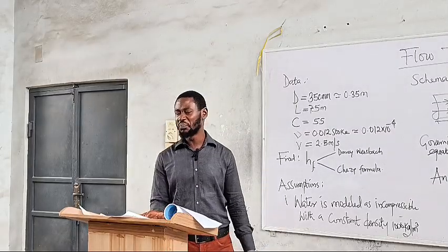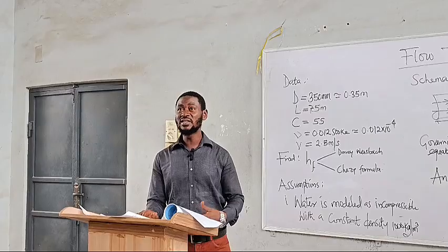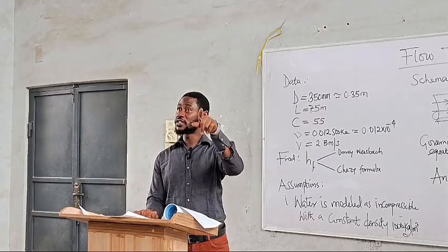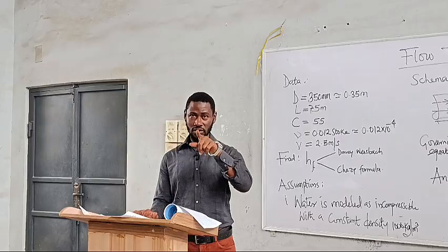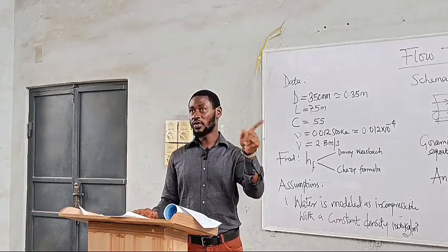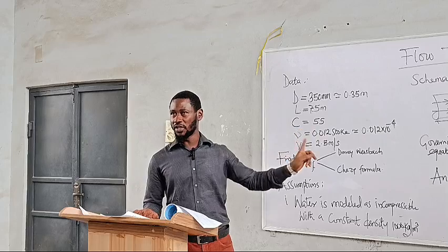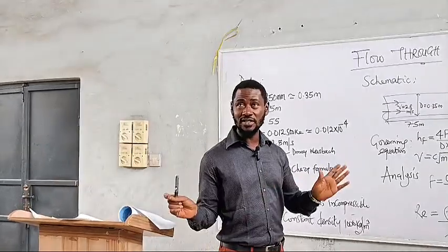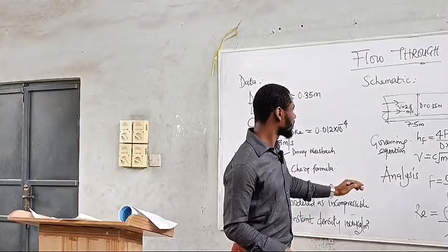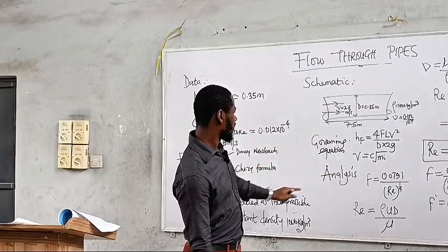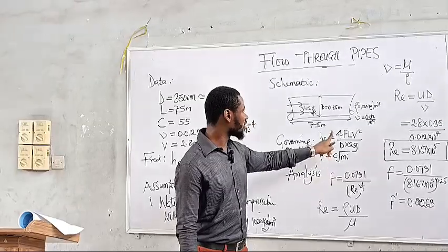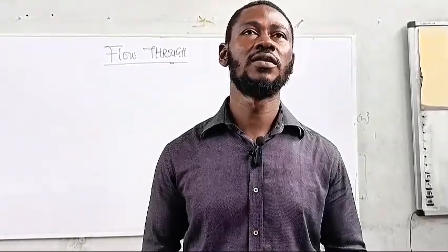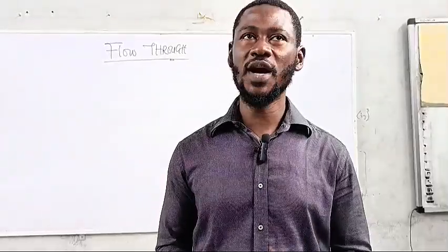For conceptual reason, both are used for calculating head loss. But F is calculated, and C is given in the question. On mathematical basis, we have their formulas to be quite different. This is for Chezy, and this is for Darcy-Weisbach.